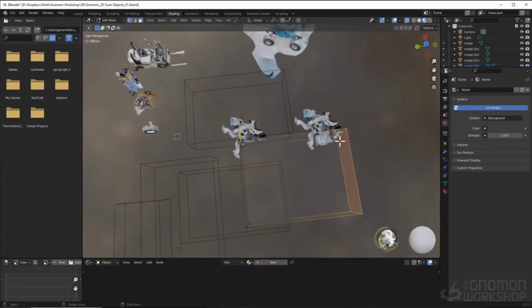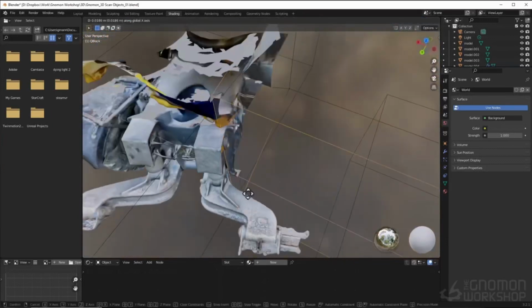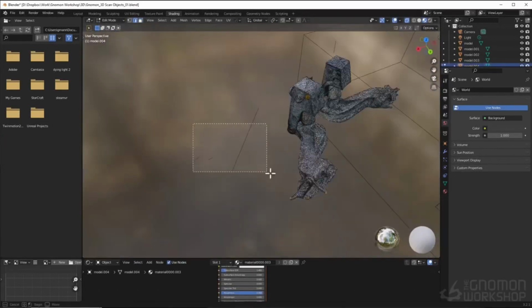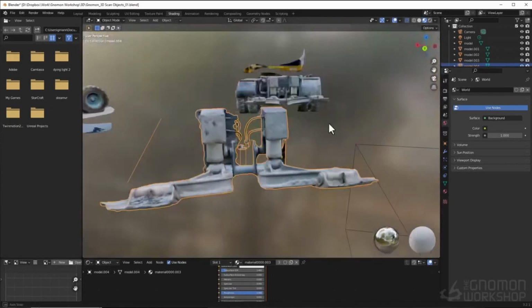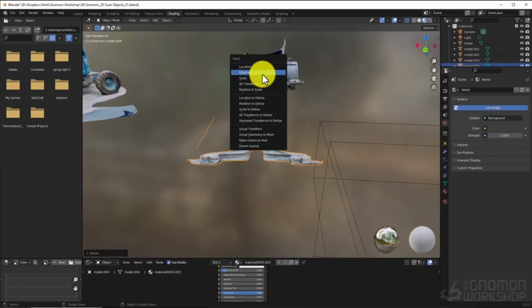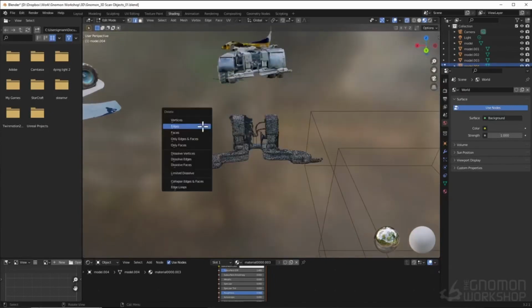You can also edit the shape of the cutting objects to get more precise cuts. Sometimes it's necessary to go into edit mode and do some manual cleanup after the Boolean operation. The next step is to apply the rotation by pressing Ctrl A and selecting rotation so that it behaves correctly when I apply modifiers to it. The reason for this will be a bit clearer later on.